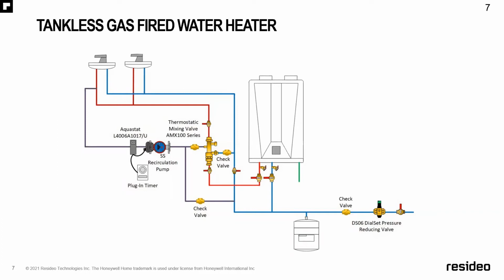And then they hop in, and a second later, you get a sudden drop of temperature at the tap. This is called a cold water sandwich. This is the recovery time it takes from the last time you had usage to the new time it has usage, because that's how long it takes for the tankless water heater to recover. So introducing recirculation will give you more control in the matter, so you don't have this issue. That's more of an annoyance.